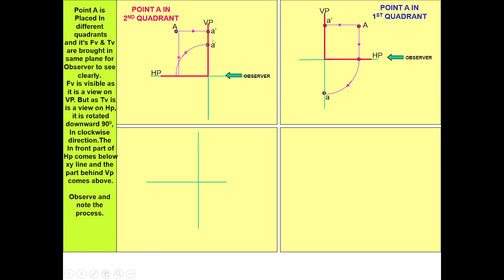So here they are both on the same plane, so we do not draw or use second angle projection. In the third angle, you get A dash, the front view, below here, and the top view here, and once you rotate, you get the top view A and A dash on the same plane.